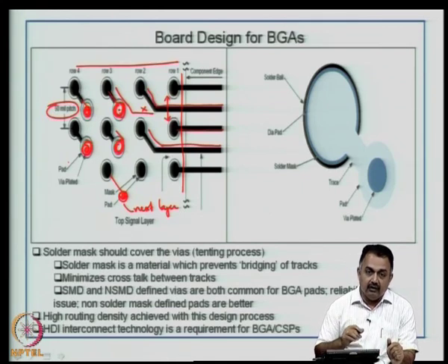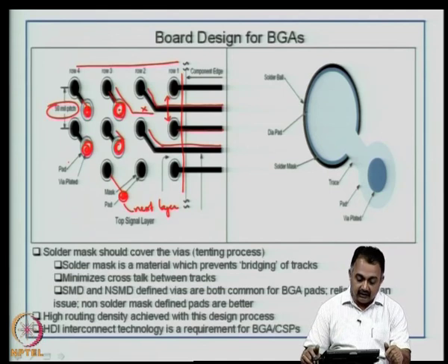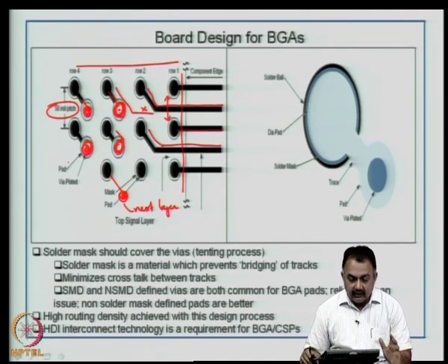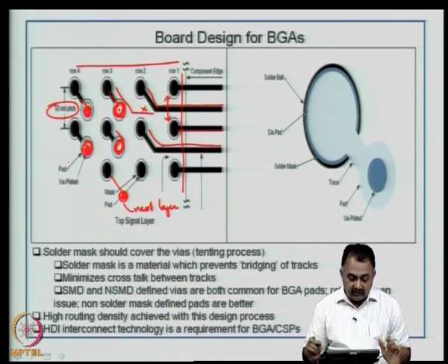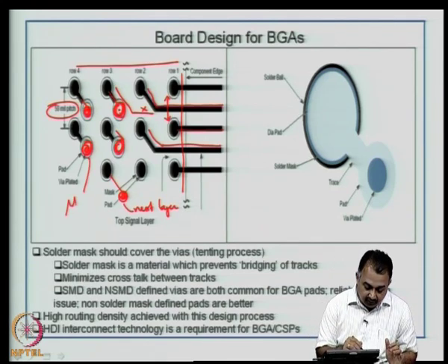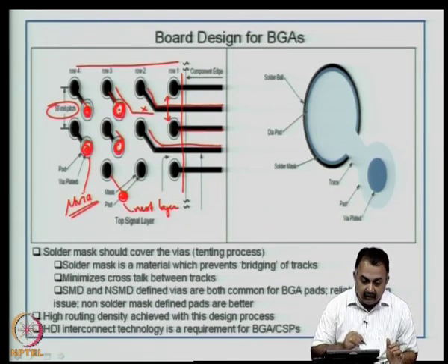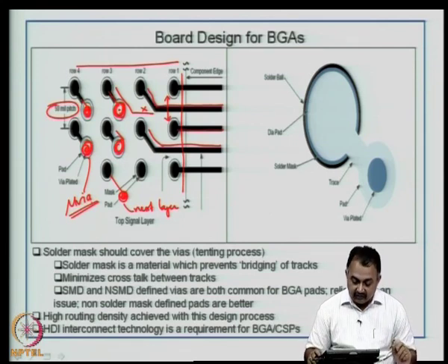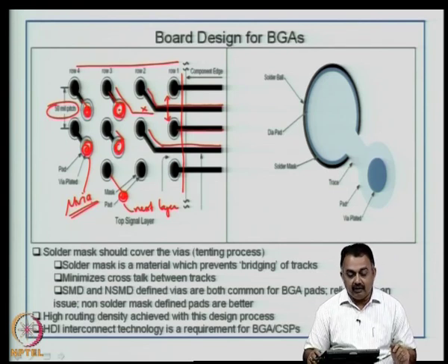So, if the number of pins or solder balls is more in a BGA, you can expect definitely a 4 or a 6 layer board. So, you need to know about creating this. This is typically a micro via that you can do. You need a small via, you can't use a very large via structure here. And typically for improving the reliability of this design, you want to use a micro via using an SBU technique, which I will explain when we come to manufacturing, and typically you do not want a through hole structure.